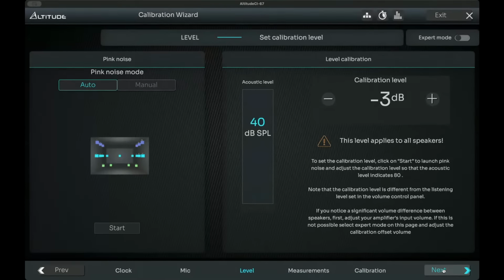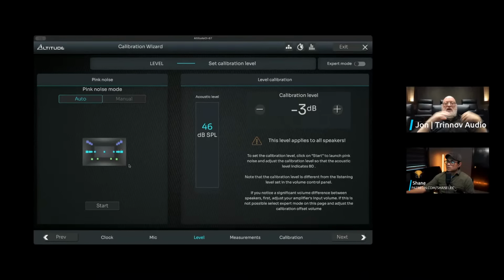The idea here being we're going to play pink noise through each of the speakers. And if they're anywhere close to each other, within, say, a 10 dB range, you don't really have to worry about this. But every once in a while, including the room that I'm in right now, there'll be a huge disparity between some of the speakers and other of the speakers. So in this room, the screen channels are, ready for this, 117 dB sensitivity, or 2.83 volts in. That's crazy efficient or sensitive.